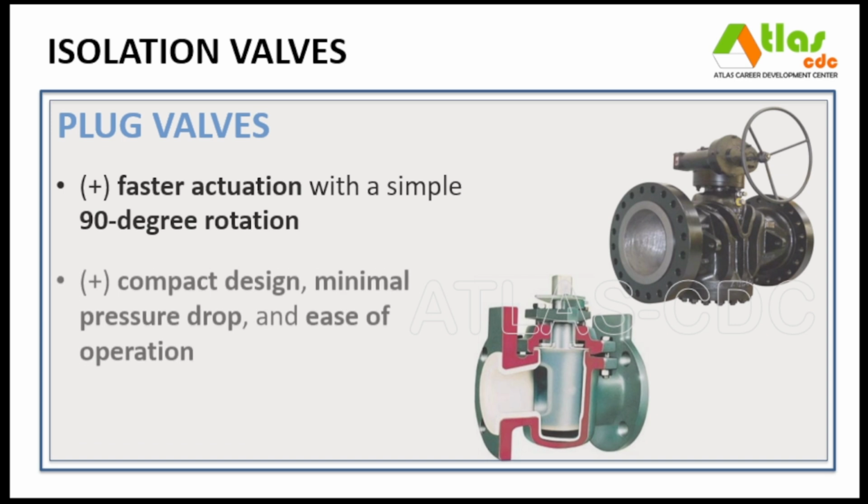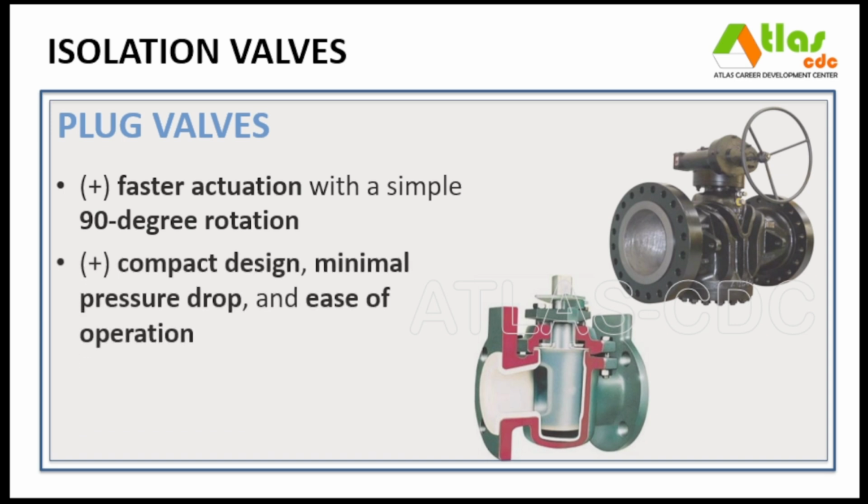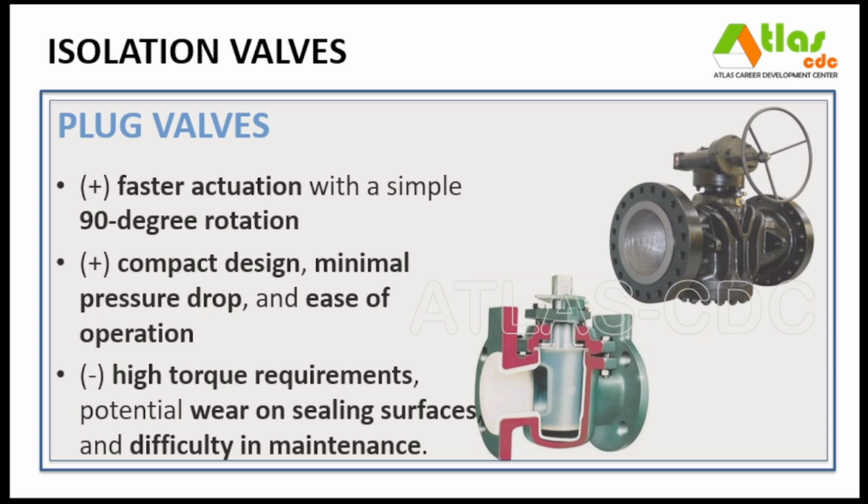The advantages include compact design, minimal pressure drop, and ease of operation, while disadvantages involve high torque requirements, potential wear on sealing surfaces, and difficulty in maintenance. Typical uses are in chemical processing, oil and gas, and water treatment systems where tight shutoff and reliable sealing are critical.